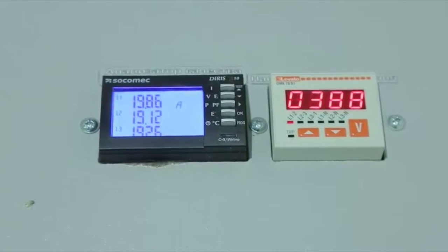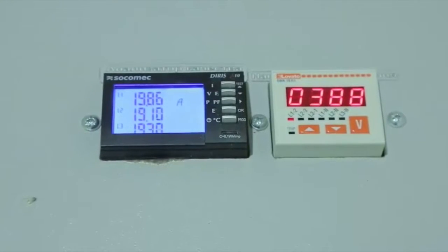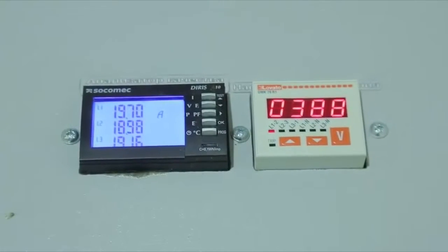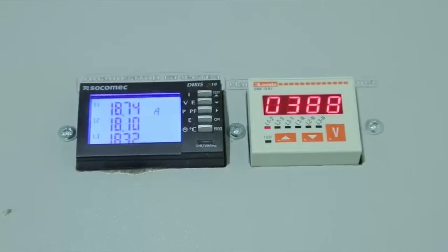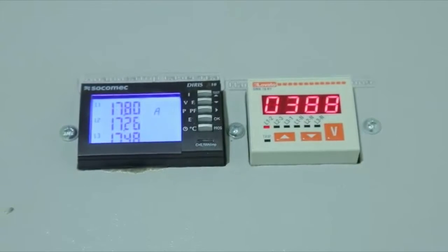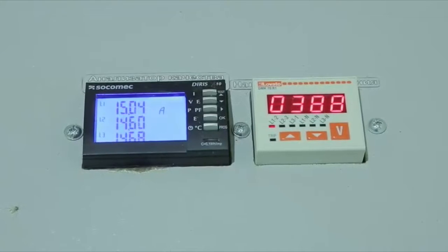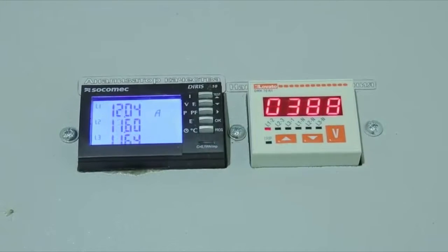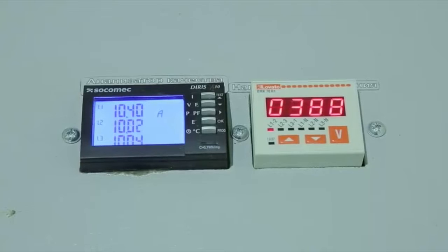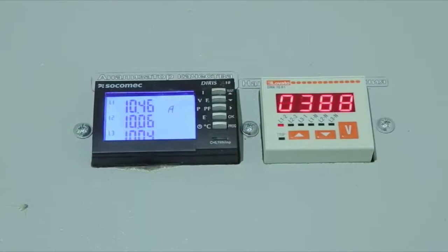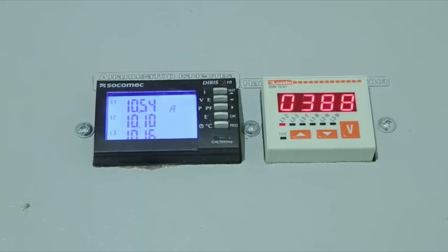We monitor currents and voltage of the set mode. The device analyzes operation of the asynchronous motor and within a time interval of 30-35 seconds reduces power of the motor without changing the number of shaft revolutions. We observe reduction of operating current of the asynchronous 18.5 kW motor. Total saving of consumed energy in idle mode is 50%.